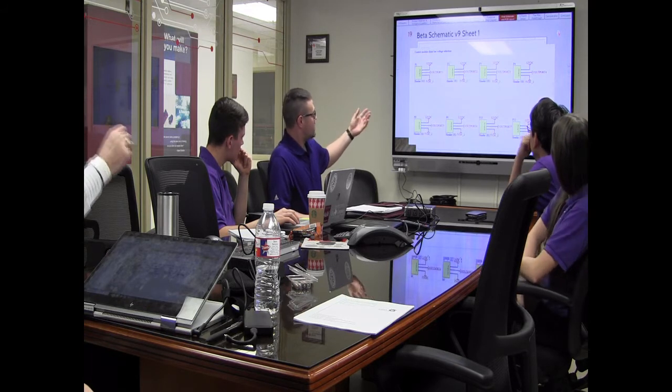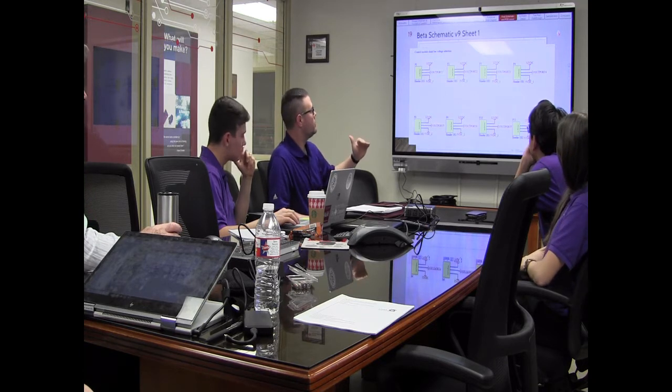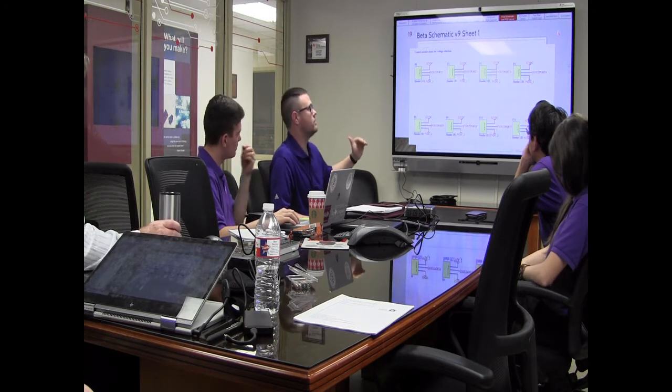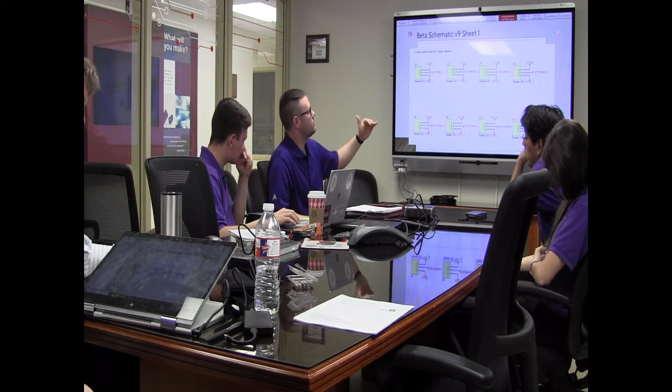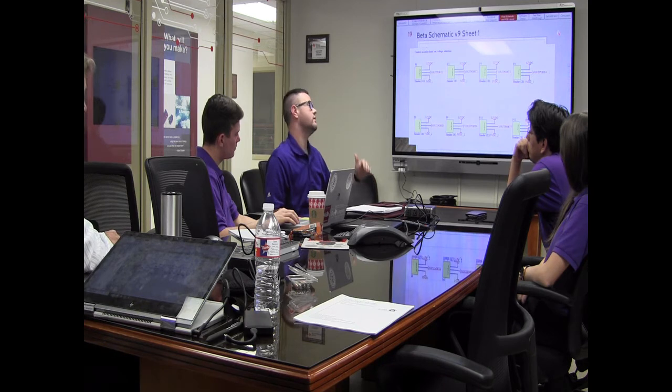Next one. Here's all the shunt motor voltage selection. So the middle pin is your V out port that goes out towards your outputs, and then you either are tying that to 12 volts or 5 volts. In either case, all the low side switches are on one of the 5 volt regulators, and all of the H bridges are on the opposite 5 volt regulator. And we're going to have documentation that shows us how to set up all of this configuration. Yes. You're going to describe each one as to what it can do.